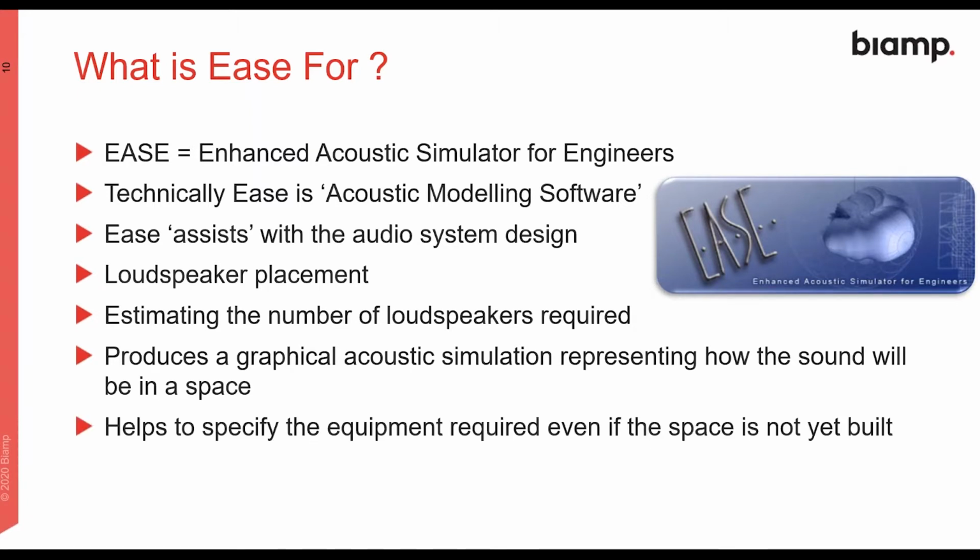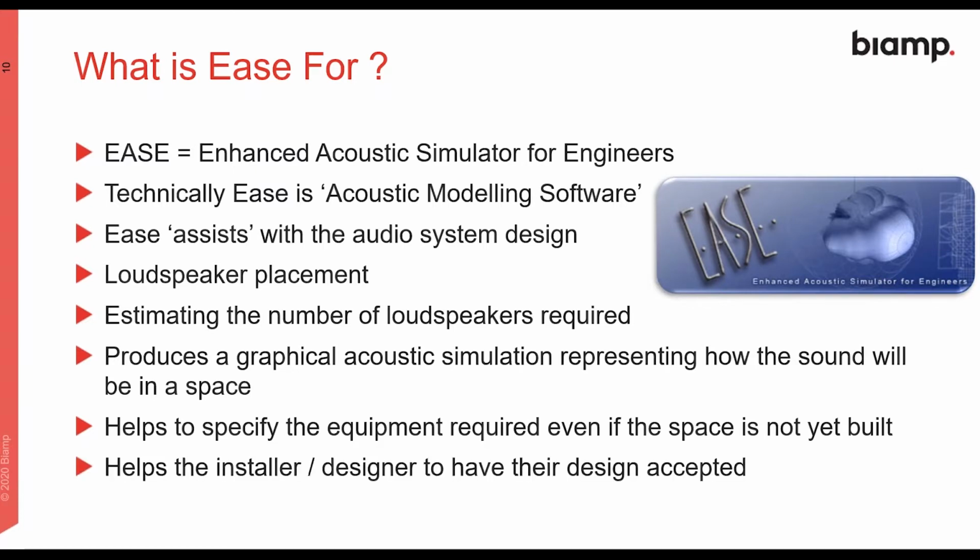This helps you to specify the equipment required, even if the space is not built yet. So in many cases, what comes out of an EASE simulation can help the designers of the building and the architects to build the space to be acoustically better, for example. And then ultimately for you, the installer or the designer, it helps to have your design accepted because it produces a very nice report at the end of the process, which goes along with your offer for a project, and therefore gives a bit more professionalism, if you like, to the bid that you're making.